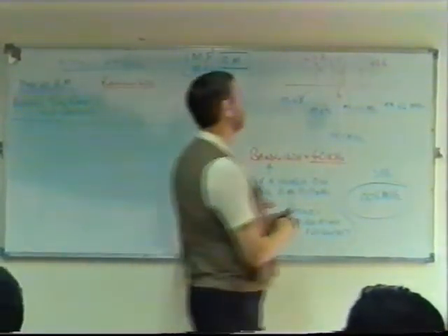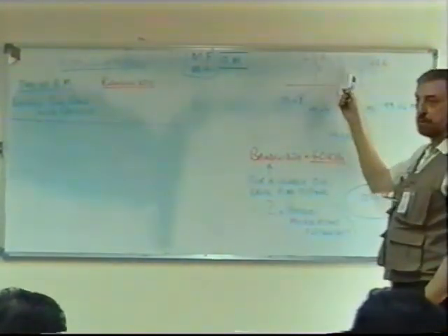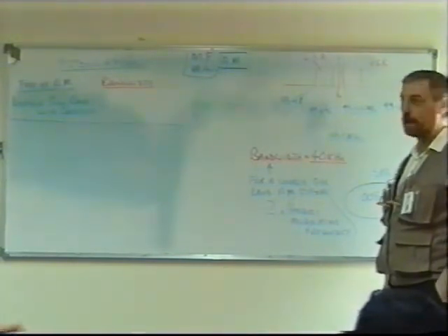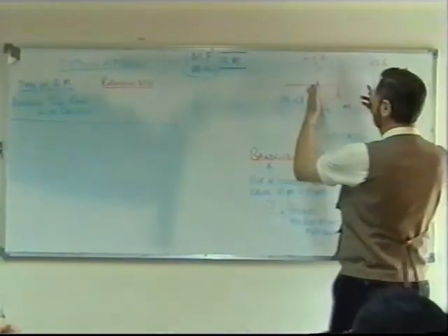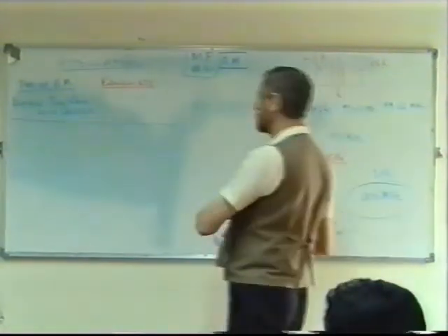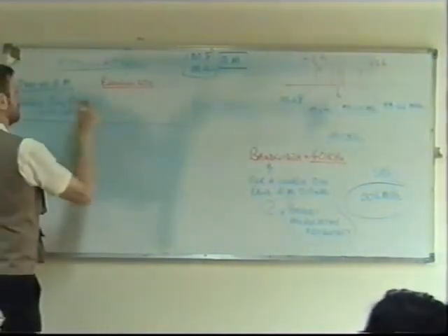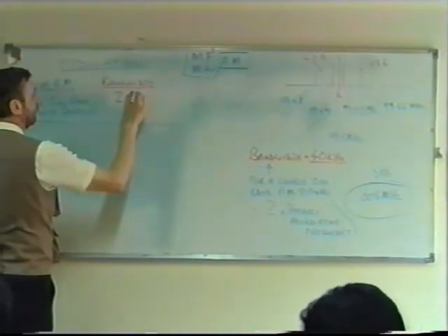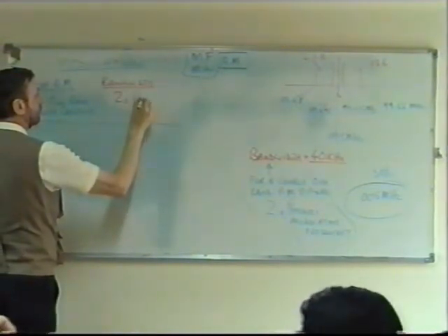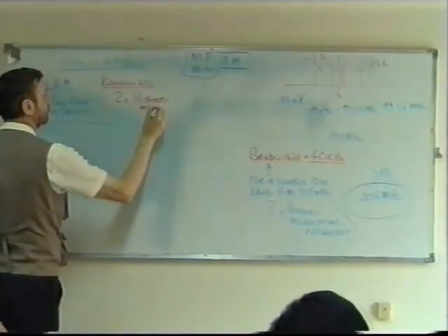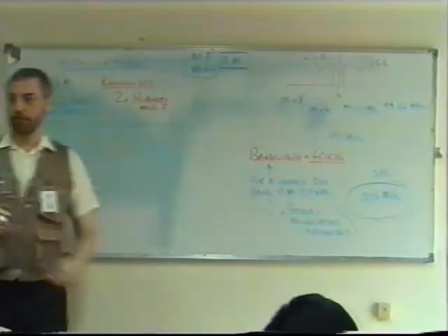Why it's called that? Because what we actually transmit is an upper sideband, a lower sideband, and a carrier. And what is the maximum bandwidth? Well, the maximum bandwidth is 2 times the highest modulating frequency. So in this particular type of modulation, the maximum bandwidth is 2 times the highest modulating frequency. I'll just put mod F there because I've already described it here.